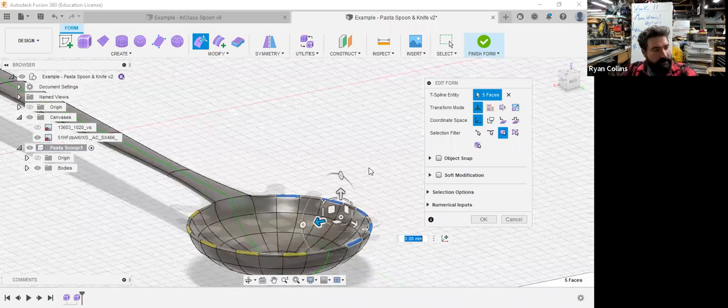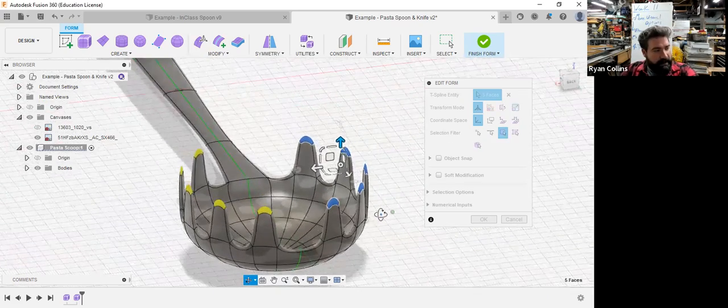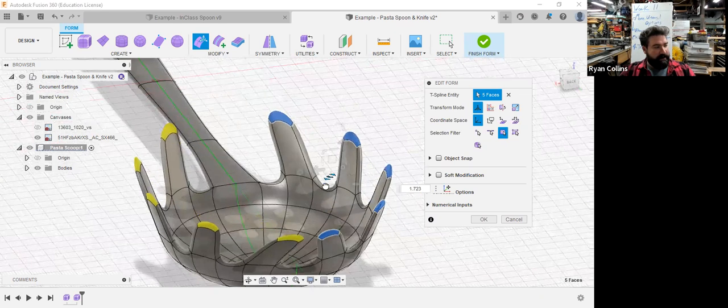So there we are. Press and hold Alt now. Drags all of them up at once. Much more effective. All right. So from here, since I have all of them selected, if I select the scale tool in two dimensions, now they can go in and out.